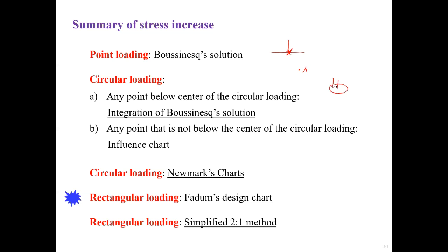So we have a circular loading, and for any point below the center of the circular area, we are able to use another analytical formula, which is the integration of the previous point loading formula. We are able to refer to that formula to do the calculation to work out the stress increase.